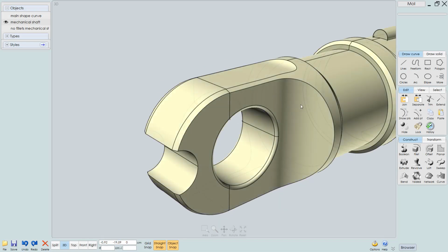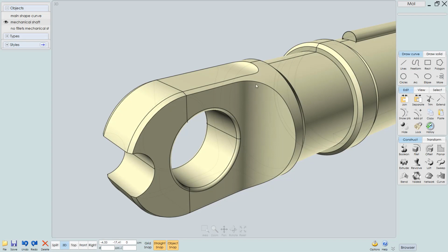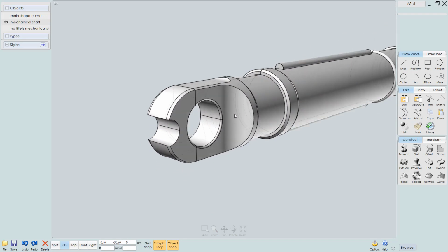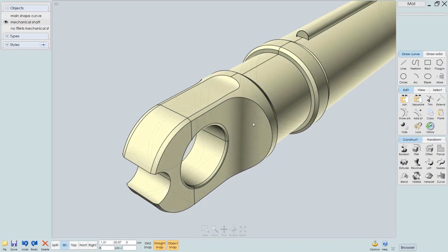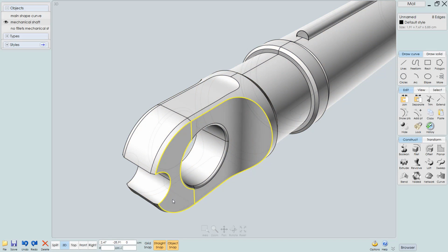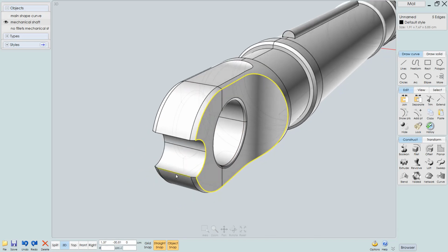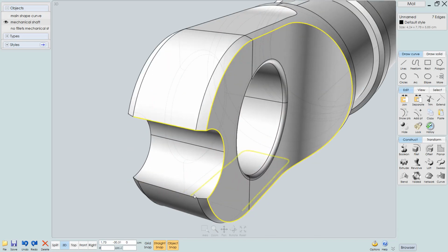Now sometimes in MoI you have to be careful and add the bigger fillets first before you add smaller details. And that is something that can be a little bit difficult to guess if you don't have the experience in Moment of Inspiration. So I'm still struggling with that, but for this object we should be fine, hopefully. So let's start selecting these edges here. I try and do a loop selection and see what happens. Now this time it's not really working, so I'm going to hit Ctrl-Z to undo that, and we just need to select all of these manually.